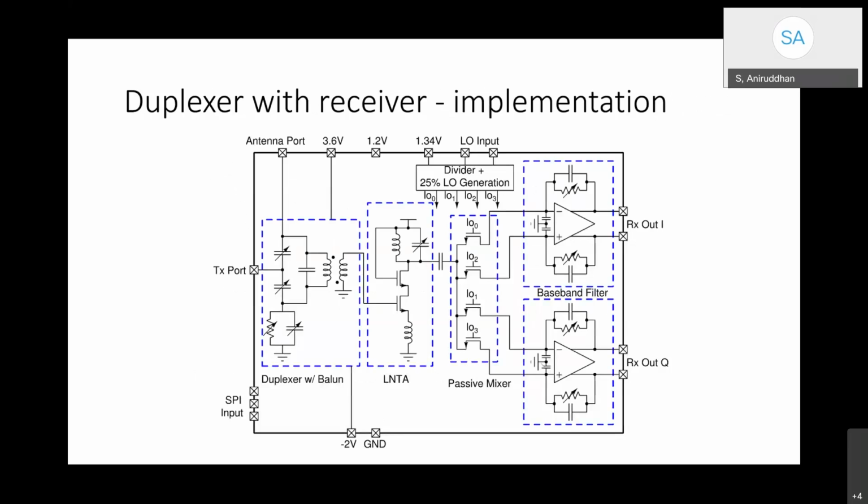of K. In our particular implementation, this shows the block diagram of our overall receiver, the self-interference cancelling receiver. I hope all of you are able to see my mouse; I'm using it to point. This portion is the bridge that causes actual cancellation. This is the antenna port and this is the balancing impedance. As you can see, C1 and C2 are made reconfigurable inside the chip. Because the output is differential, we are doing differential to single-ended conversion using a transformer, and that goes into a fully single-ended receiver.